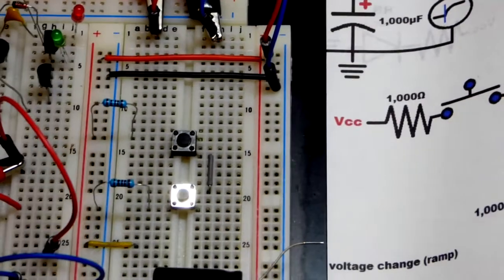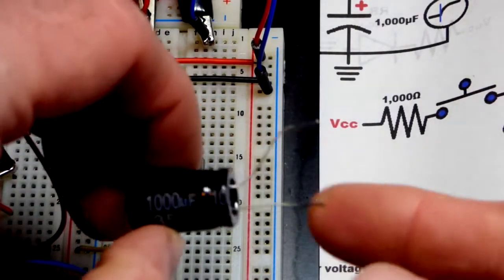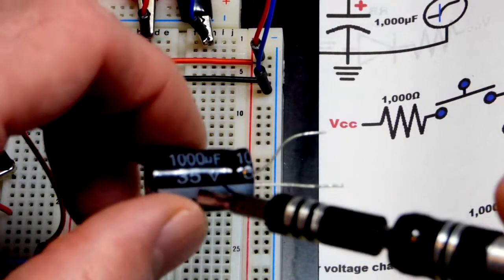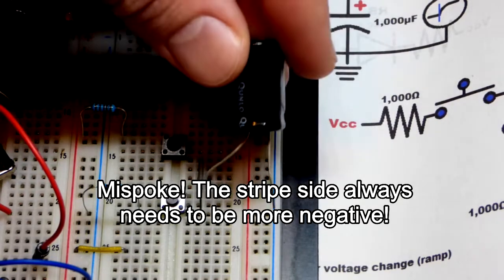And we will add the capacitor. There you can see a little better. It's a 1000 microfarad capacitor. We can charge it up to 35 volts. That side has to be more positive. I forgot to mention that in the last video.